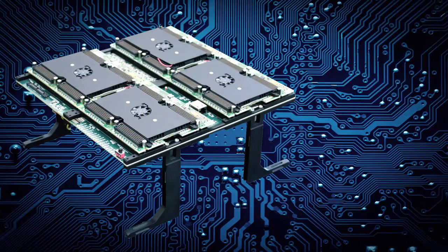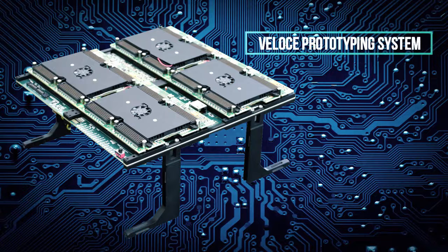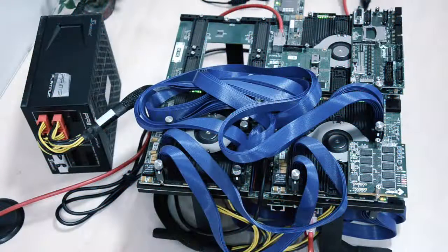The quad-core SoC has been implemented on a Veloce prototyping system having 3 Virtex UltraScale VU440 FPGAs, with a capacity of 25 million ASIC gates each, which are interconnected through high-speed FRCs. The quad-core design comprises about 30 million gates, and uses 2 FPGAs in the system.